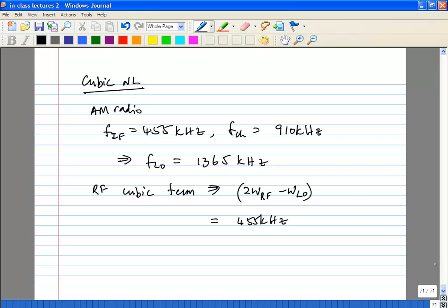The main reason this comes about is because your output frequency band is not the same as the input frequency band. Earlier, in the case of the LNA, any cubic terms would fall far away from your desired RF signal because the output frequency is the same as the input frequency. In this case, your output frequency could be much lower or much higher. So you could have problems even with a single input.